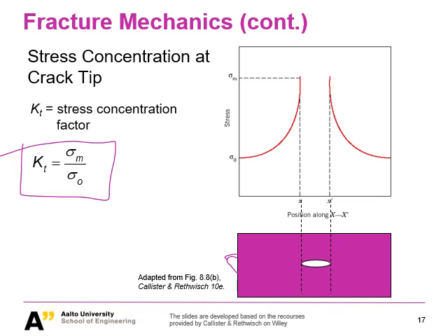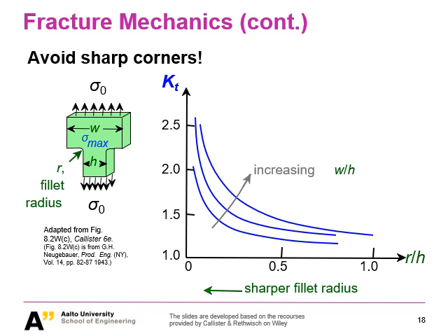And what is interesting is you always see, when you go from the crack tip into your, let's say, matrix, the stress gets such a profile, and it reduces from high to low. And this actually gives you already a very good design principle, let's say, or prevention rule to avoid brittle fracture.